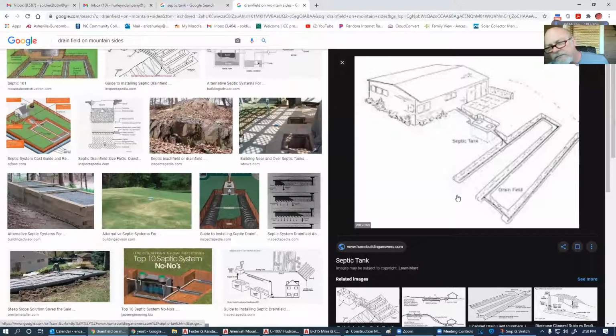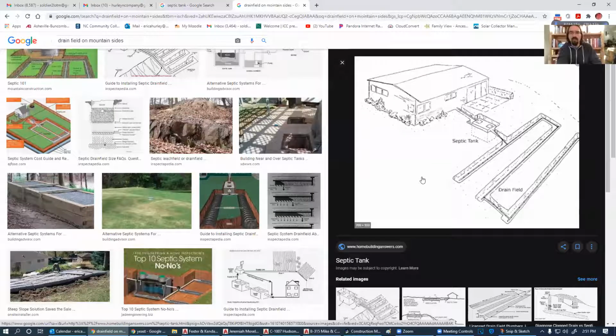I like that one. So you can slope down, but at that point you've got to be level. You can slope, level, slope, level. I don't think that would work, because you've got to be able to get all three of these distribution equally, and they wouldn't approve for that. Not in North Carolina, not in Burke County, maybe some other places, but not here. Looks like you'd need a box on those corners too.